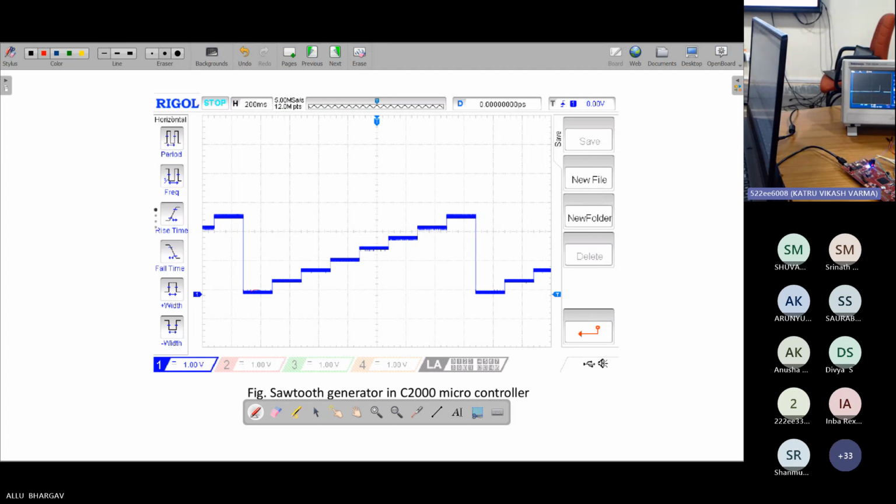To overcome this, enhanced pulse width modulation pins have been introduced, and due to this, without the use of sampling time of the model, we can select our frequencies based on the system clock frequencies. So in EPWM, how do we set it to generate the sawtooth or triangle pulse using the system clock frequencies?